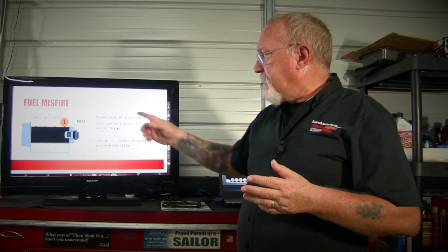because of that misfire. But if you can catch it on your freeze frame, just to recap, if I go into freeze frame and I know I've got a P0301 for cylinder 1, and I can see that the fuel trims for that bank are increasing 3 to 7% more than bank 2 was running, total fuel trim, then I may think, well, maybe that's telling me it's an ignition-related event. And if I see it up in the 20s, I'm thinking fuel.